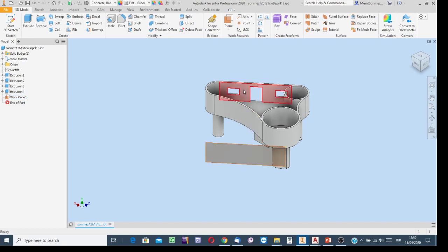Although it is possible to draw the sketch over this flat surface to create the empty space within that curvy feature, in this scenario there are lots of things already created to their boundaries, so drawing the sketch over this crowded surface will be difficult. To make life easier at the sketching stage, that's why I defined such a work plane.